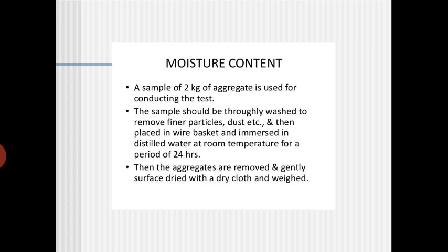Even if more dissolved solids are there in water, if you immerse aggregate in it, an aggregate reaction is going to happen. For example, alkali aggregate reaction is one best example. When alkali aggregate reaction happens, water is required. I already said that water is most important. If water consists of more alkali, that is nothing but dissolved solids. These dissolved solids are going to react with the alkali and disintegrate it, and it will change the property of the aggregate.